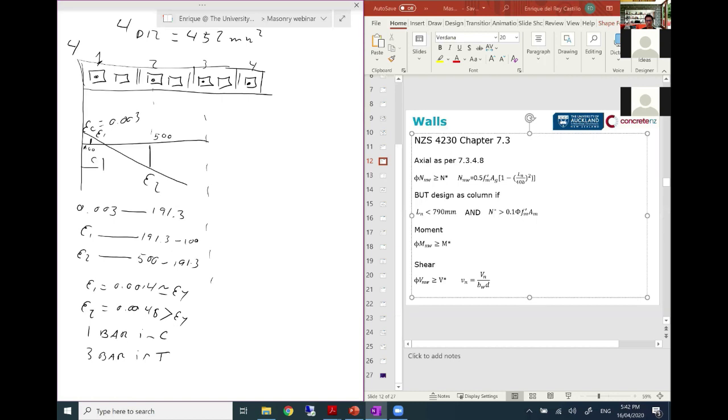So now we can calculate, sorry, I forgot to obtain A, which is A1 plus A2, 162.6, and C, which is 191.8. Now we calculate the compression force coming from the steel.